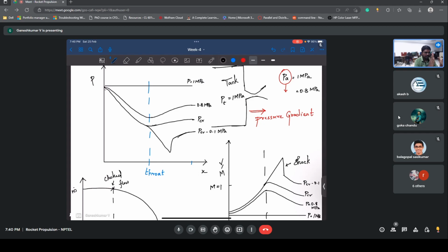But if I reach Mach number 1 here, I am also moving at the equivalent of sound velocity, so there is no way I can send information to the upstream. So my convergent portion is going to get fixed, and it's not going to change at all thereafter, once I reach Mach number 1 at the throat. Then there is enough pressure gradient to have a fully isentropic flow also. So I will keep accelerating, but suddenly my pressure is very high at the back.